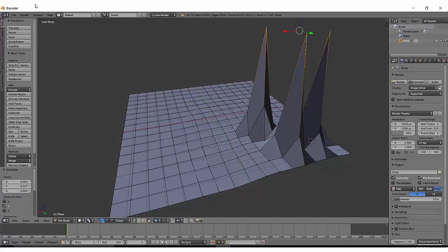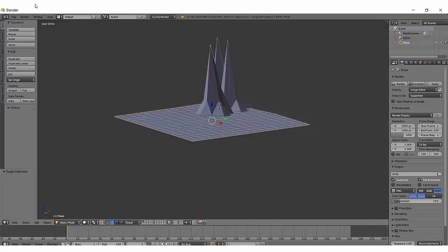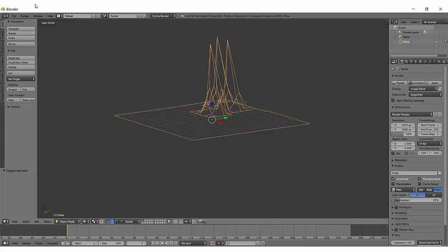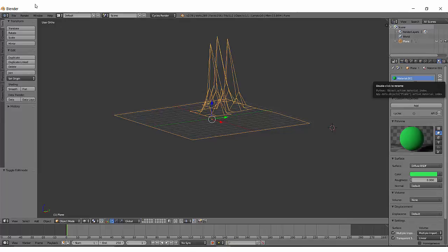Now as you can see the vertices, you can adjust them in all dimensions using the X, Y and Z coordinates. Now go to orthogonal mode to obtain a view like this and press Z to obtain wire mode. After you obtain the wire mode of the image you have created, go for adding materials as shown in the figure.